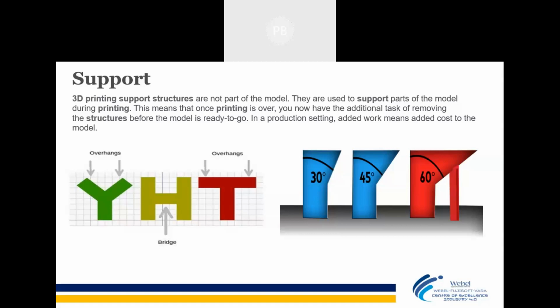Thickness. Sir, the thickness of the material which we are depositing. The thickness or the height of the material, right? Each layer that is deposited. So layer height is also one of the factors in 3D printing. Whenever you are doing 3D printing, layer height is one of the factors for your surface quality or for your time duration. So layer height plays a very major role. Whenever you are printing in a 3D printer, layer height can be controlled from 100 micron to 300 micron. You can put any layer height from 100 micron to 300 micron.